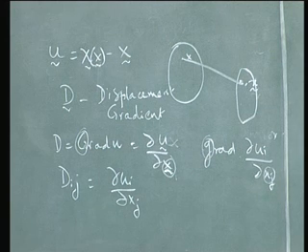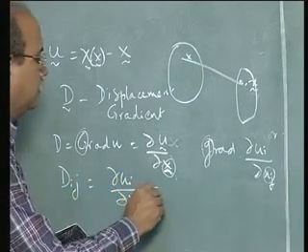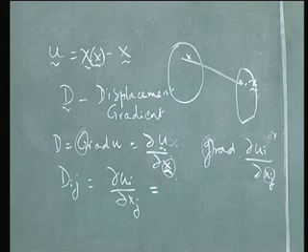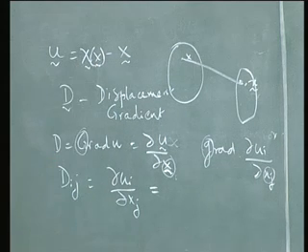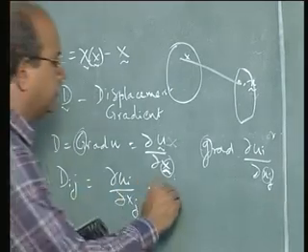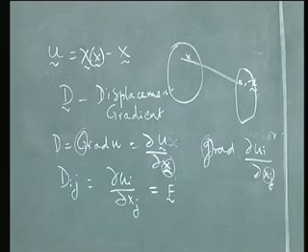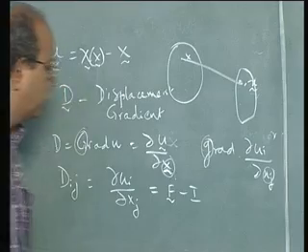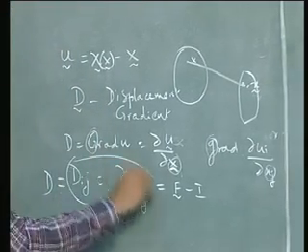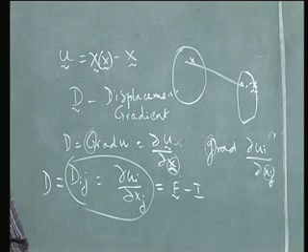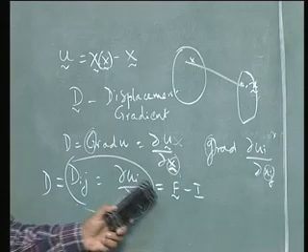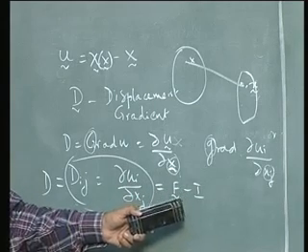Let us see how you define D in terms of this. It's very simple. I can extend that by differentiating this with respect to capital X. So the first term here becomes the deformation gradient tensor F, minus the second term becomes I. So D, which is given by this, D is equal to F minus I. Is that clear? Or Dij is equal to Fij minus Kronecker delta ij.